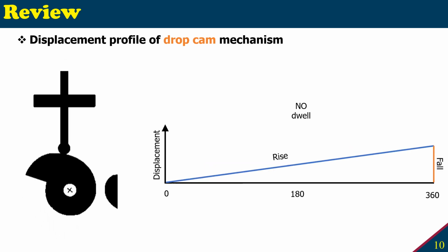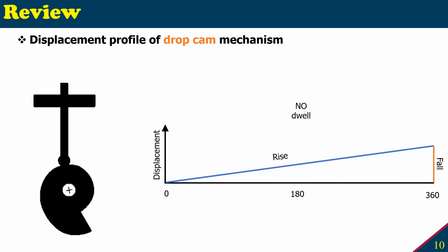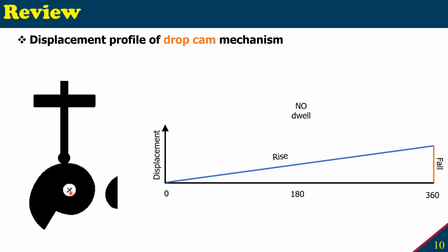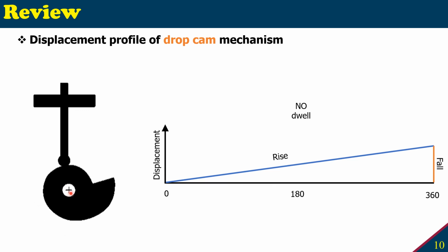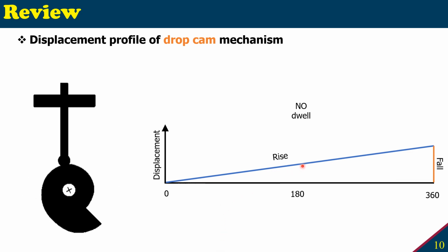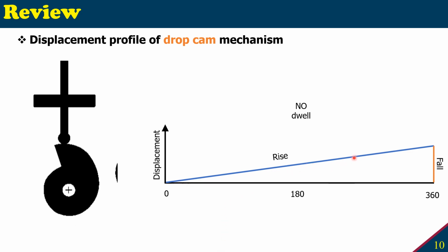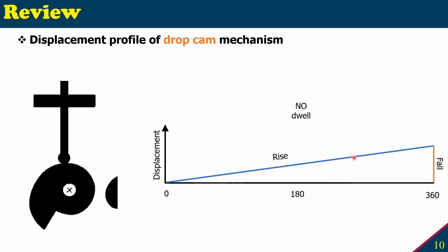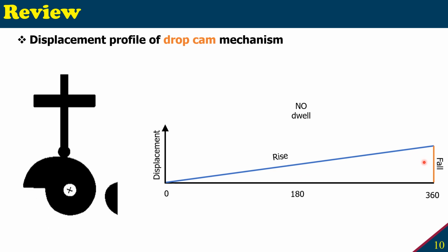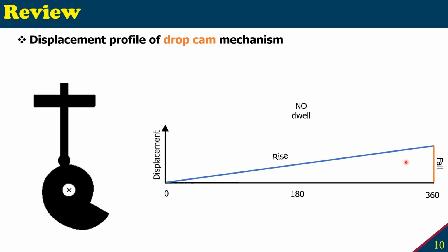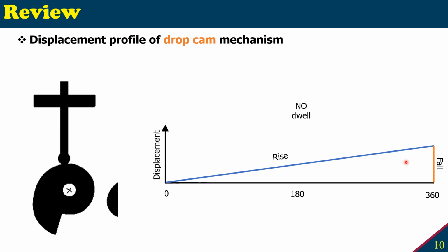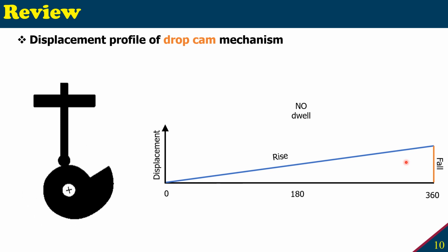So our fourth and last cam mechanism is the drop cam mechanism. It is also called snail drop or spiral mechanism. It is based on the Archimedean spiral that gives a triangular non-symmetric profile when you use the cam mechanism. It linearly increases and then suddenly drops. It has no dwell period, and it can only work correctly if we use the knife edge follower.